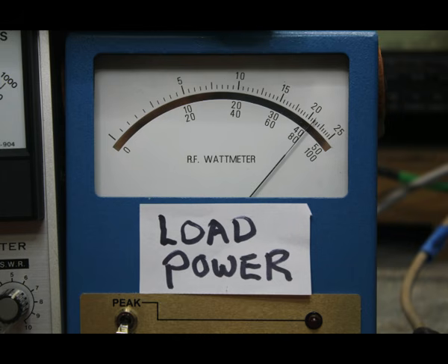It proves that we don't have a bunch of reflected power bouncing around inside the coax. All that power has done is gone back into the cable and established a standing wave. All the power is still flowing from the transmitter out to the load, and all that imaginary reflected power in the transmission line is doing is establishing a standing wave that changes the impedance. It changes the ratio of voltage to current all along the length of that transmission line. That's all it does. So we can't go to a table.